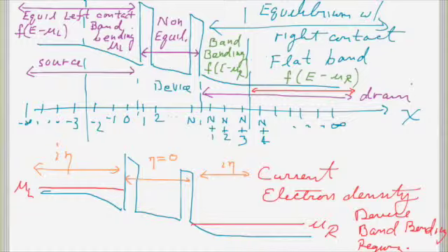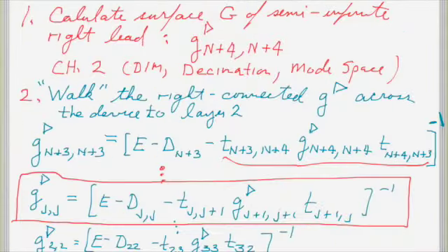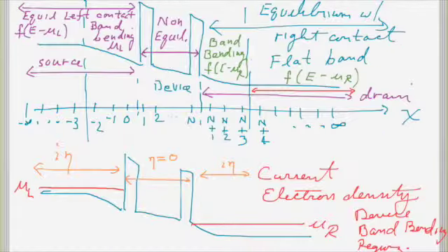So what that means in terms of what we just did here, for all the D's, the diagonal blocks that are in these equilibrium regions to the left and right of the barriers, we can put an i eta on the diagonal elements, and that will give energy broadening, and it will do other things for us that we'll talk about later.